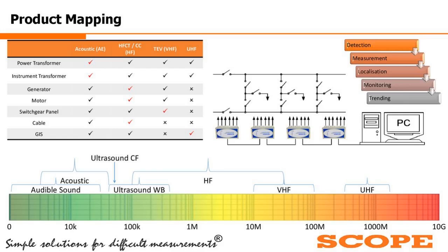So there you can have those inputs in these data acquisition units, and with the help of these units, they can form a chain of hundreds of such units. That is, 600 data points can be taken care of by one network, which can be monitored in the PC. So this is a monitoring system which detects and localizes the partial discharges. This is the 24/7 monitoring solution that we just discussed. Earlier ones were the portable ones. All right. So for all the equipments that you have, you can adopt this particular technology for your continuous monitoring.